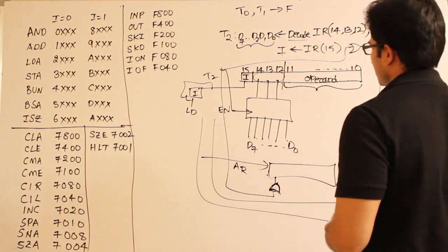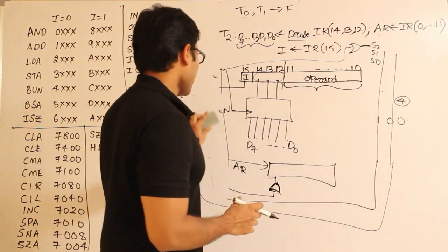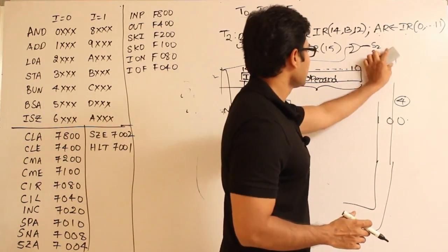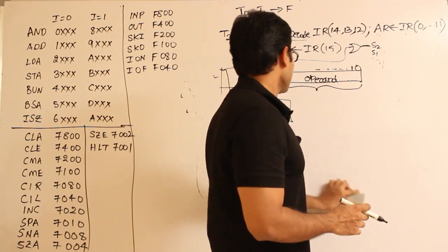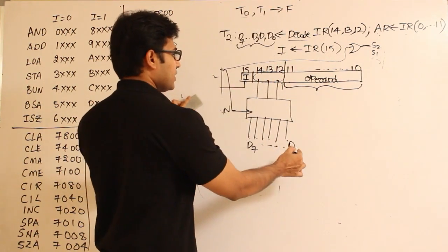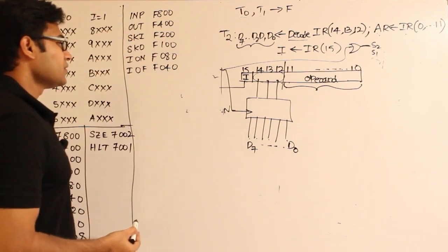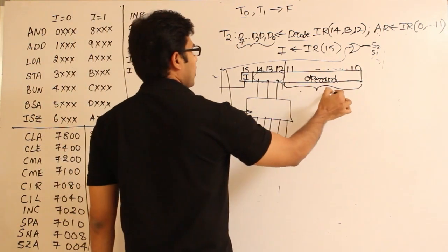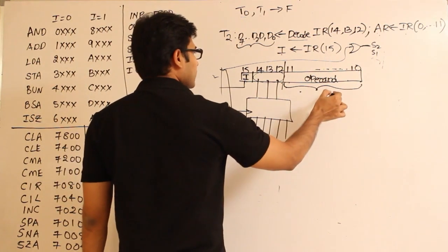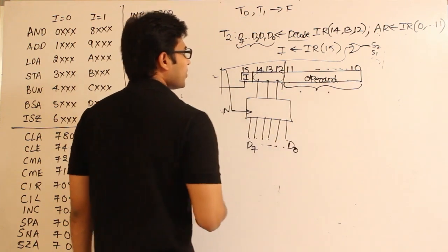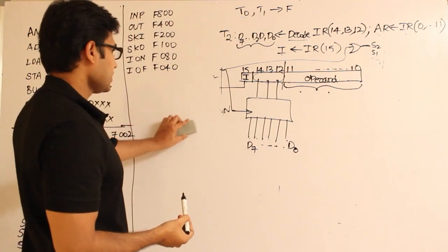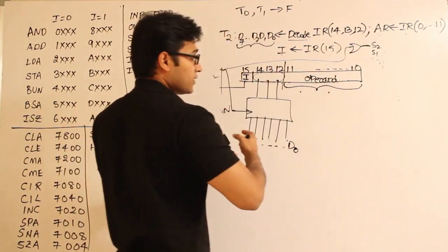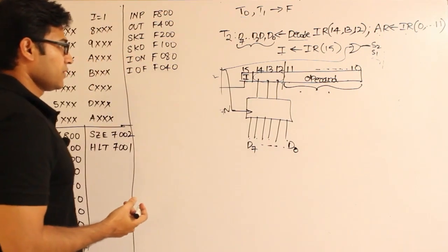Depending on the output of this decoder, you have to understand what type of operation it is. So if you see this, since we are using only 3 bits, it might look as if we have only 7 or 8 different types of instructions, but that is false. The reason is, I am not always going to have this operand field as valid. The operand field will be valid only when there is a memory reference. Otherwise, if it is a register reference instruction, I need not use this. In that case, I can increase the number of instructions. Got it? So see this.